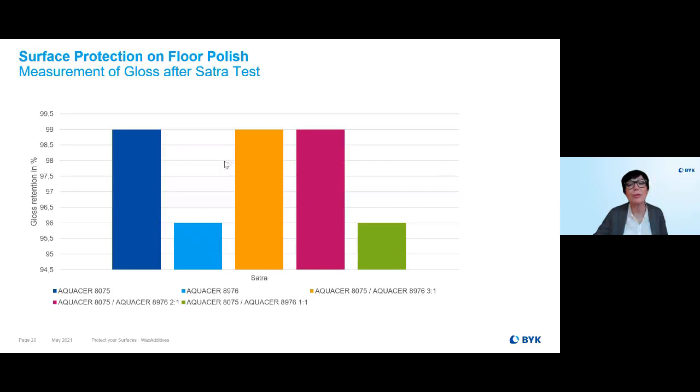And if you compare the different mixtures of 3:1 and 2:1 polyethylene and polypropylene, the gloss remains the same like the high density polyethylene, and just by using a bigger amount of polypropylene, we see that the gloss is getting down again by about 4 units. So it's still okay, it's not a big damage, but at least you can see here pretty well the differences.